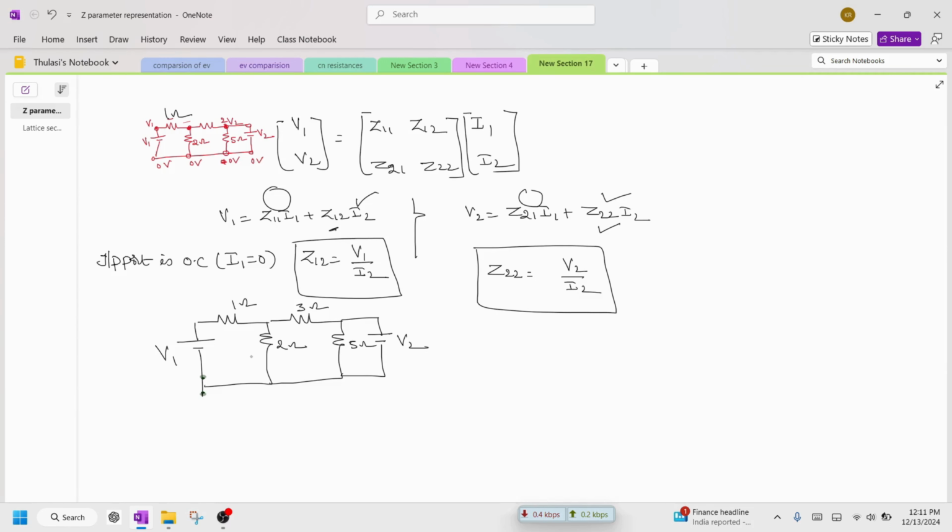So now what we are going to do here is, we are making I1 as 0. The current in this branch, we are going to make it as 0. Whenever you are making the current as 0, what is the voltage created? So voltage V is equal to I into R. It's nothing but 0 into 1, voltage is 0. Open voltage is 0 means indirectly the current is 0, indirectly this acts like a short circuit. Therefore, the network is transformed as like this.